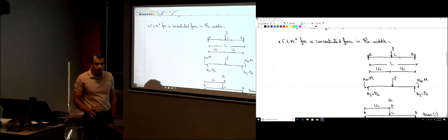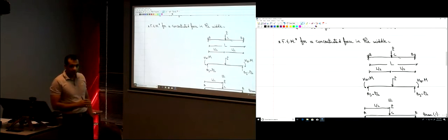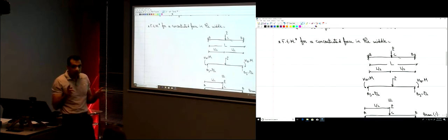Do you know any information that would help you to find M? I know that this is a fixed beam, right? By definition, you're trying to find a fixed-end moment M, so you're fixing A and B. So the deflection and the rotation at both points A and B are zero.